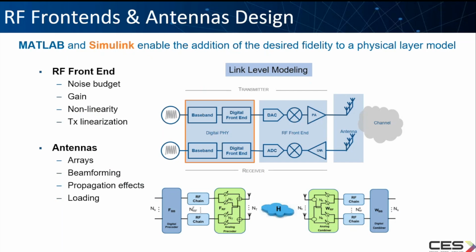MATLAB and Simulink enable the addition of the desired fidelity to your physical layer model by allowing you to design the front end that will include the noise budget, the gain, the nonlinearity, the linearization, and so on and so forth, or by modeling and integrating antennas that can be arrays or array signal processing like beamforming. You can also include the propagation effects and the channel effects on your signals. And